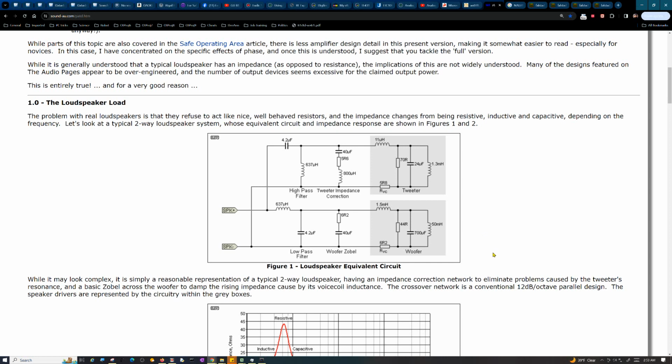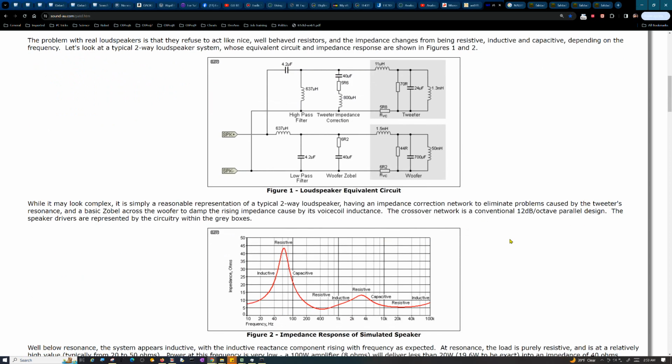But I haven't read it yet. Basically, with a power transistor, the higher the voltage across it, you've got to derate the transistor way below what you would think its power rating should be. You may think, oh, this transistor should be good if I run it at 50 volts, I should still be able to get an amp out of it based on the calculations. But no, because of the safe operating area, you might be lucky to get 100 milliamps out of it at 50 volts.